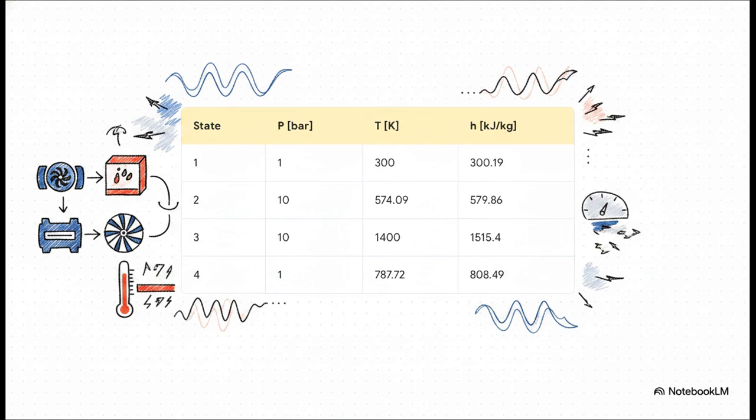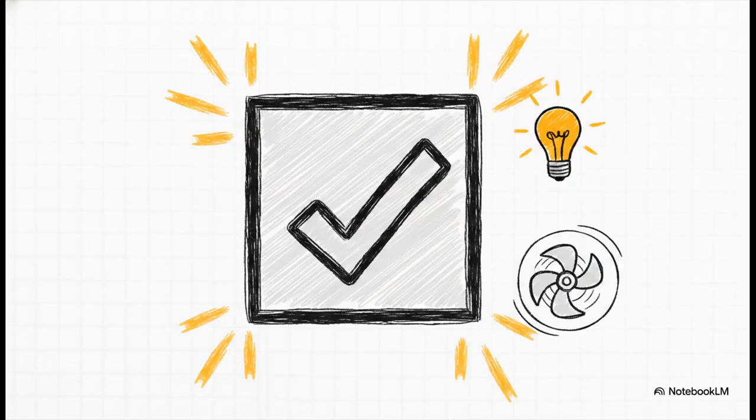By meticulously mapping the pressure and specific enthalpy at every single state, the virtual system successfully hits that massive 70-megawatt load requirement. And guys, this was a massive win for the simulation. The OpenModelica Brayton model was square, which just means it had an equal number of equations and variables. It successfully flattened, or instantiated, and most importantly, it reliably simulated the steady-state power generation. When the equational math perfectly aligns with the software architecture like this, the capability of the tool is just breathtaking.